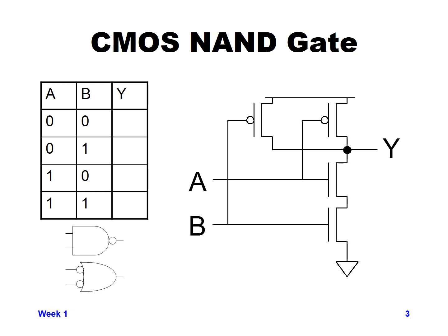Typically in CMOS, the C stands for complementary. And it's complementary from the standpoint that the number of transistors of NMOS going to ground are typically always equal to the number of transistors of PMOS going to VCC, but just organized differently, so that we get the logical function out. So that's why the C in CMOS stands for complementary, and you'll see patterns as you go forward in how this logic is organized.